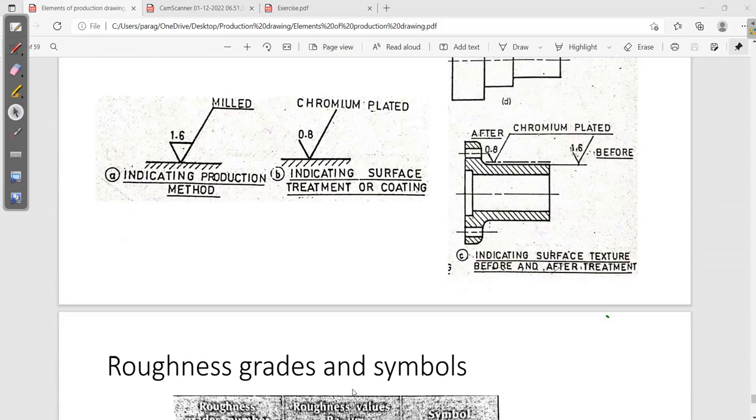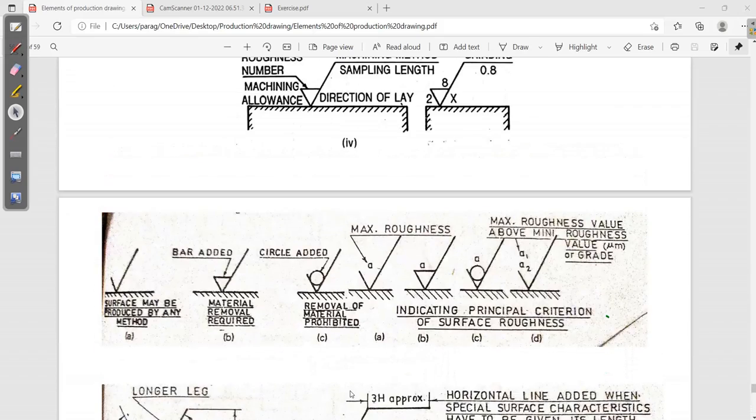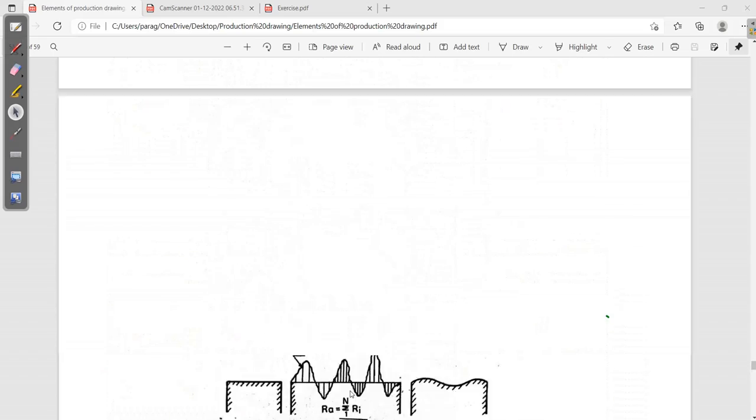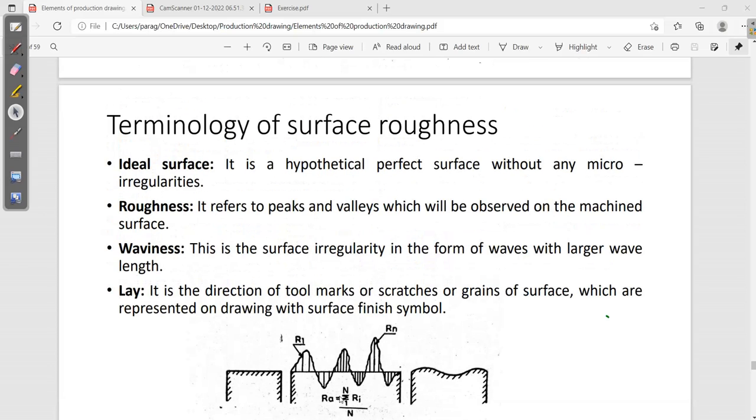Okay, so this is about surface roughnesses. Now in this case, every time you can do a drilling operation, boring operation, milling operation. First of all, in manufacturing processes, I already told you, after drilling operation we are doing what? Boring operation. Why boring operation? Why are we performing that? In order to make the hole smoother.